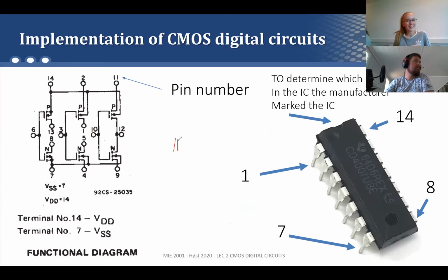If you remember the NOR logic gate, I just draw the P part, okay? Then the NMOS is down like this. I don't draw the N part. This is the top part of the NOR logic gate. The bulk of the top PMOS is connected to VDD. The bulk of this one is connected to VDD here, because all the bulk has to be connected to VDD.